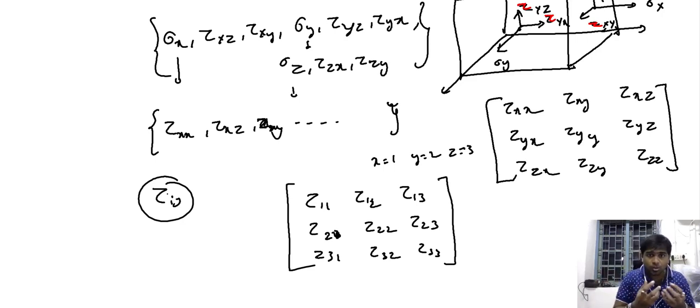And when you consider all the possible combinations of these indices that dictate the value assumed by the tensor, it can be represented in the form of a matrix, and we were able to do so for the stress. So essentially, stress is not a scalar, but rather, in the generalized stressing setting of a triaxial tensile loading, and particularly when our focus is on the inclined plane, the comprehensive way of describing a stress would be in the form of a tensor.